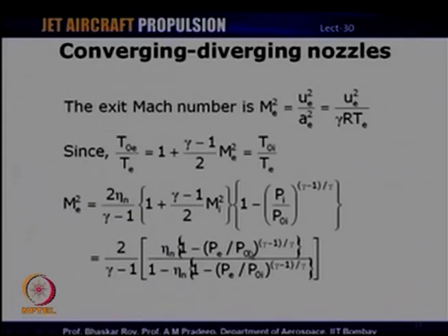to the inlet pressure, and so this will be useful in determining whether we get a sonic Mach number or supersonic Mach number. Especially in a supersonic nozzle, one would want to have supersonic Mach number at the exit. So, we can find out what is the pressure ratio that will be required if we have to achieve a supersonic Mach number. Let us say we want to achieve a Mach number of 1.2.